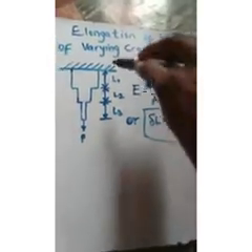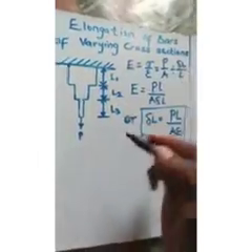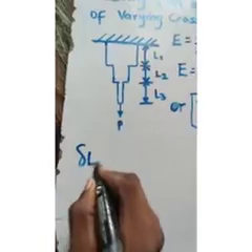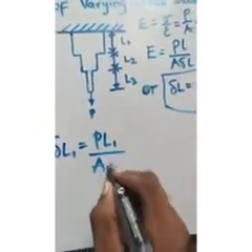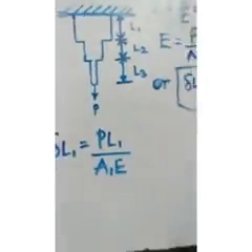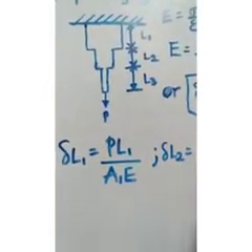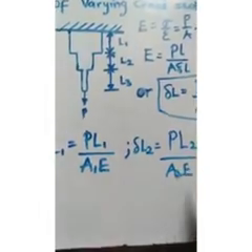Now applying it to each distribution of this length of this load, this is axial pull. So for L1, the change in length for L1 will now be equal to P L1 over area 1 times E. Also for L2, the change in length 2 will now be P L2 all over A2 E. Remember that Young modulus is constant.